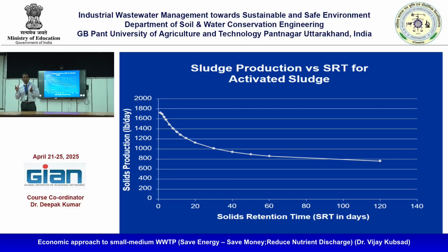Earlier your focus was measurement. Measurement of how much quantity of sludge is produced. That was your focus. But I'm going to stretch this further. If the sludge is produced in big ponds for the food industry, what happens? Your one-third volume is covered already by sludge. So your volume is reduced. How is it going to be economical? So that is why continuous removal of sludge is required.